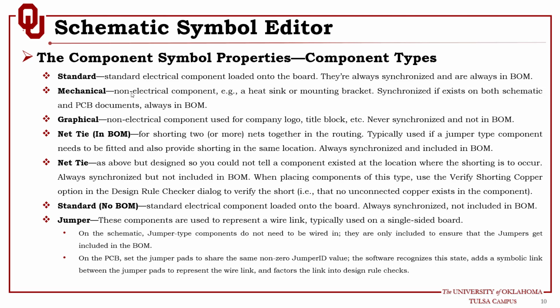By synchronized, I mean they are always synchronized between the schematic and the layout. So if you have a symbol in the schematic, you always have a footprint in the layout. And the pins of the schematic have matched pads on the layout. So if you change this component on the schematic, it will change on the layout as well. That is what is meant by synchronized. This is the standard component. This is what you use all the time, and this is what we have been using in our demonstration projects.